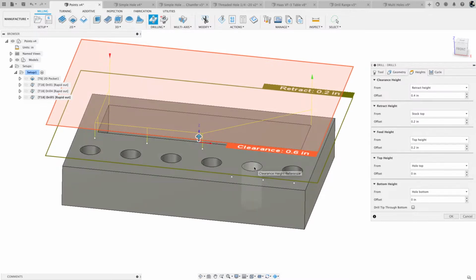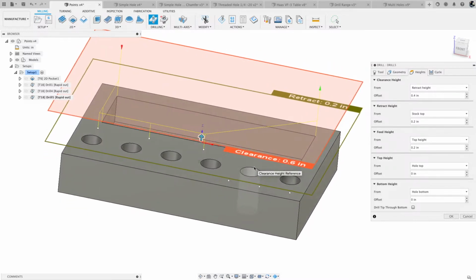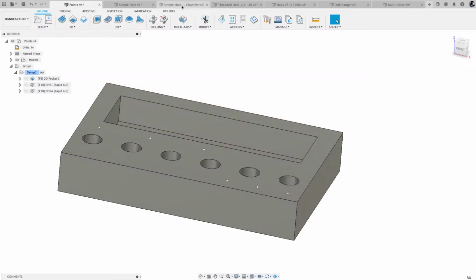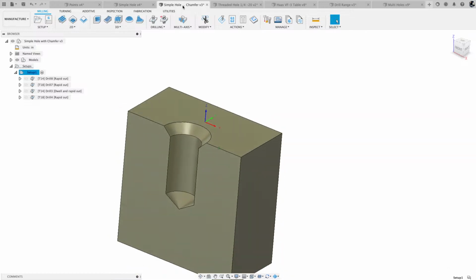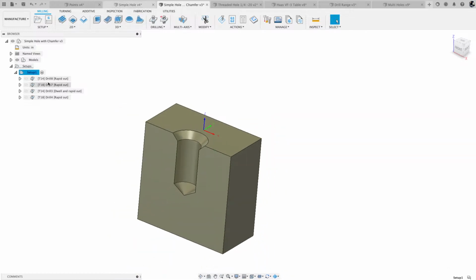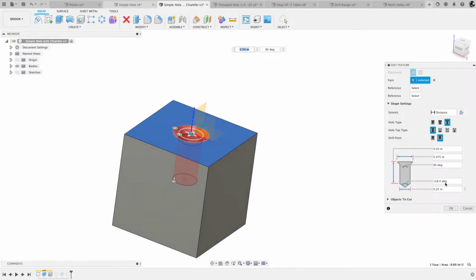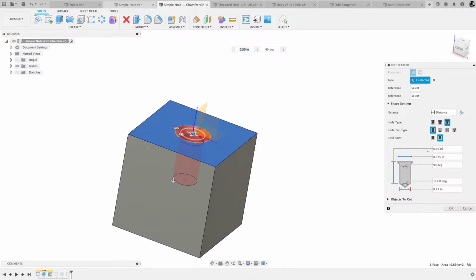Leverage the model that your customer gives you, because anytime you move a hole, change the hole diameter, change the hole depth, like we did on this one here. I can even, like I said, come down here. If we go to design, if we change that hole depth and even that chamfer, so here the depth of that hole was 0.5.